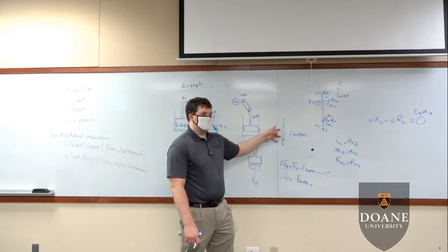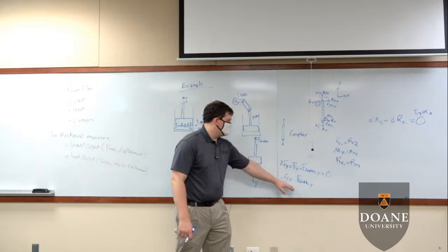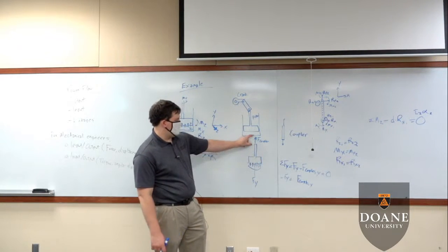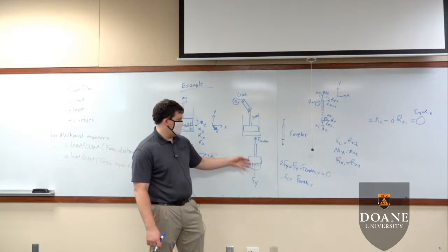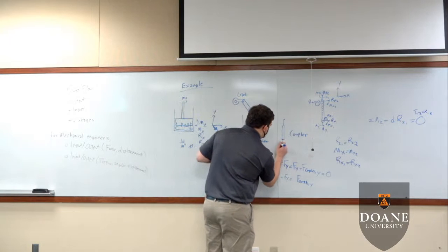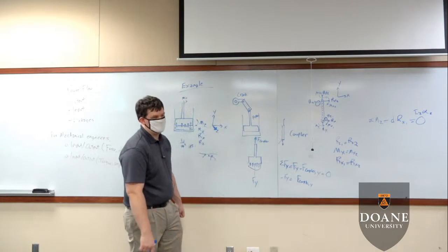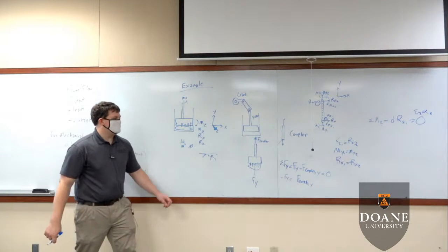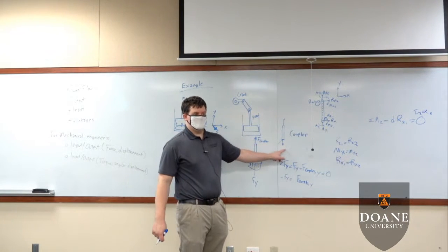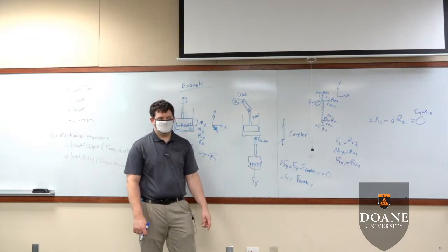This coupler can only carry a force along its axis, right? This force has to be Fy in the y direction, which at this point is actually pointed like this at the coupler. Is the actual coupler force going to be larger than or smaller than Fy?